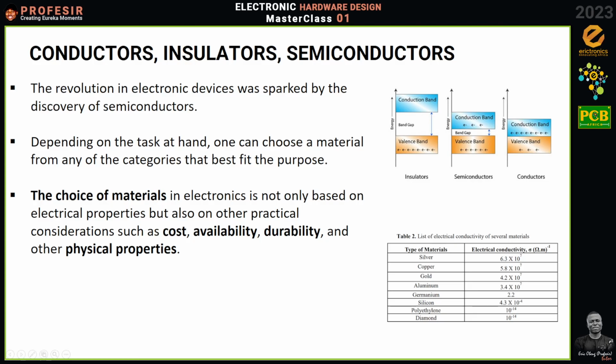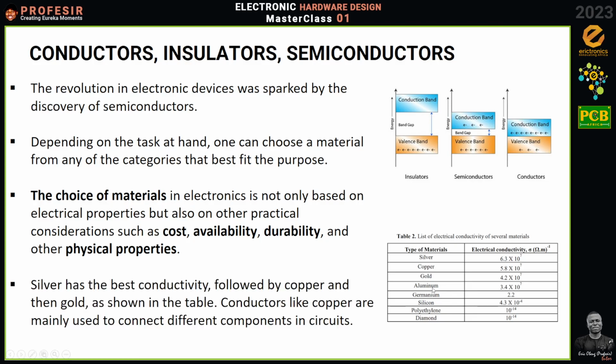Of course, there are instances where we talk about aluminium, and though aluminium is the fourth best, sometimes we choose aluminium over copper because aluminium also happens to have some properties that make it ideal in certain situations. For instance, high tension cables, right? You don't use copper, even though copper has a superior conductivity than aluminium. They use aluminium because aluminium is lightweight compared to copper.